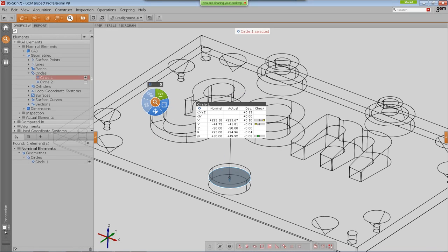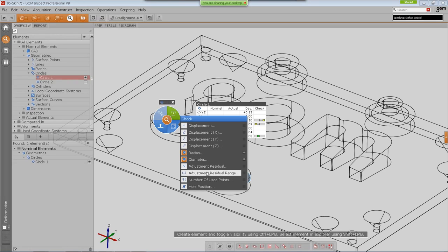If you have a look at the iInspect, and if I change right now the deformation to the deformation skin, you will see that the GD&T alignment or the GD&T functionality is not displayed anymore inside the iInspect. And if you have a look at the offered checks, this is also no longer a distance X and distance Y. It is a displacement.